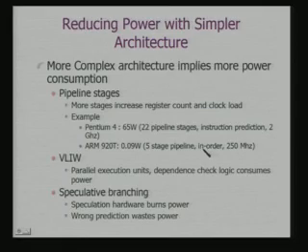Also the other reason is the use of additional chip area. Now, an interesting feature: if you go back and remember, ARM had conditional instructions, and conditional instructions were used to make your pipeline flushing overhead much less. That also eliminates the need for a kind of predictive execution to make optimal utilization of the pipeline.